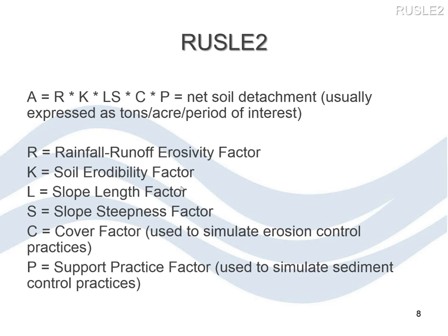Soil erodibility, it's the K factor, and that's very much tied to the soil texture. It's also tied to things like the percent organic matter and what the soil structure is. We'll go into a specific example on how all those things work together to determine how erodible the soil is, and soil erodibility is really a measure of how readily that soil detaches.